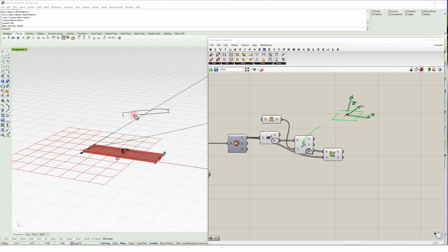So if I look at that in elevation, the midpoints of the other faces are below that, and then the highest face is going to be here on the top face. So that's what I'm sorting to. I'm going to grab that point and be sure that I always get the top face. Okay, and that's basically what the sort list component is. It's going to say sort using the keys by the Z, and then what am I sorting is an A, and that's going to be my faces here. So that's what's going on.